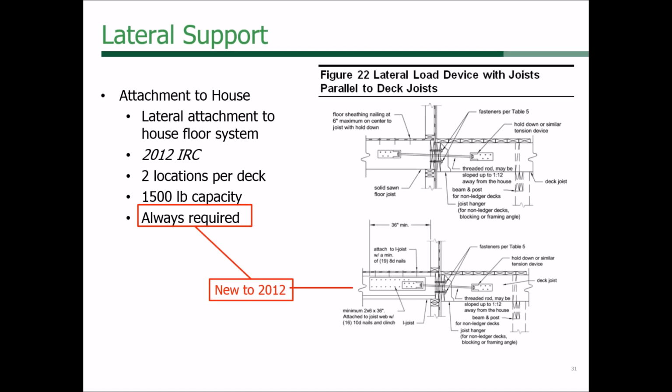But the IRC specifically states that lateral load needs to be addressed in decks, but it doesn't say how much lateral load or what that lateral load really is. So when they give this option of, look, this satisfies that, we are taking it. We're saying, if the IRC says that's enough, then we're going to do that too.